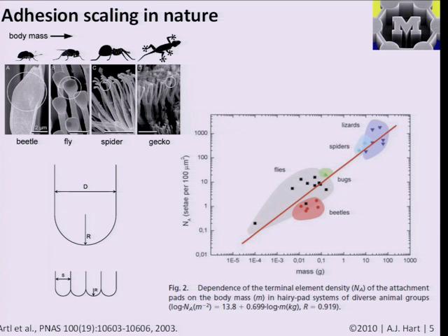And the paper touches very briefly on how the mechanics of supporting the weight is derived from a balance between the van der Waals forces, the adhesion forces, and the elastic stiffness of these contacts. And by idealizing each toe as a hemisphere, you can use classical theory of contact mechanics to calculate the force that would cause a certain deformation of the tip here.